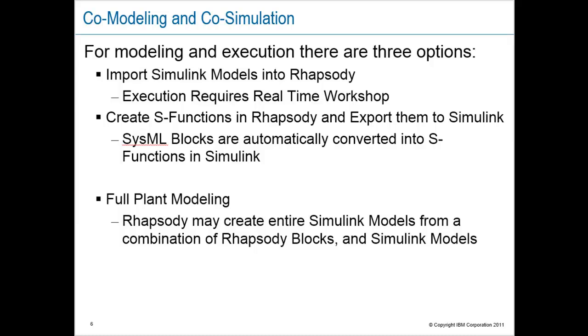There's no real-time workshop required, since Simulink itself is going to perform the execution. But also, if you want Rhapsody animation at the same time, then you can have it. You can get real co-simulation between the two tools. Now, working in that mode, Rhapsody can even be used as a template tool to lay out which Simulink models you're going to need and how they should be connected. Rhapsody can then generate all of those models, leaving the Simulink engineers to fill in the details. Let's look at these options actually in the tools, starting with full plant modelling.